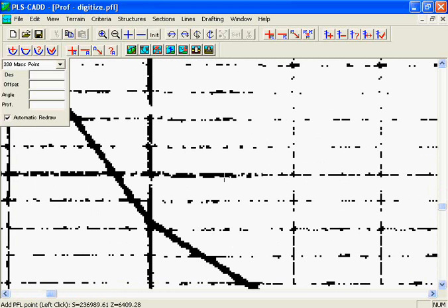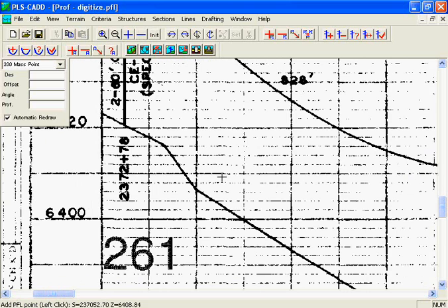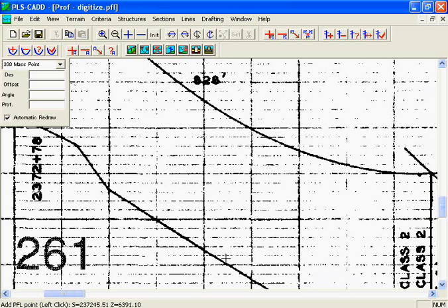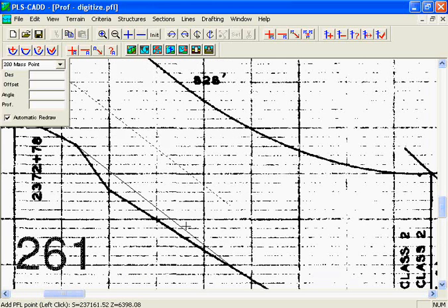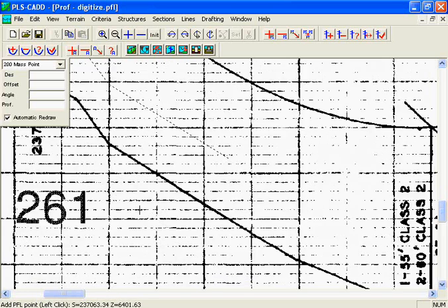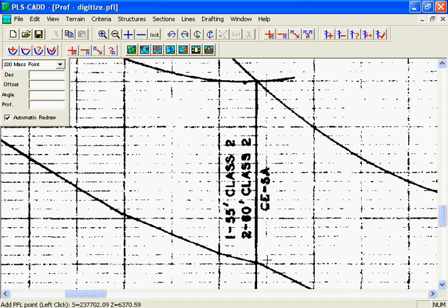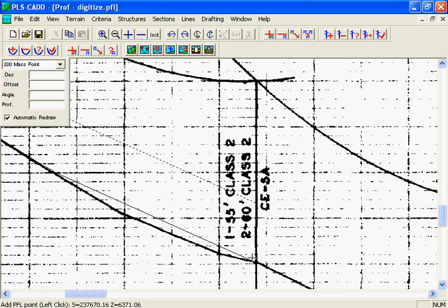Now, as you notice, sometimes it's hard to see the center of the profile. Don't be afraid to go further than you needed to. So I'm just going to pick a point down here, and now we can quickly see that I did miss some points in here. So I can put my mouse on here and get more accurate each time I click. Again, we can click further than we need to, and then clean up the changes as we go back through there.